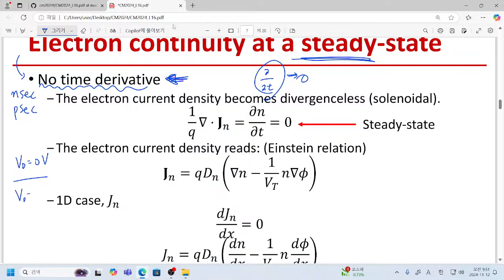Suddenly you increased the voltage up to 0.7 volt. So it introduced a huge difference in the boundary condition. What will happen? The device will take some time to reach a new steady state solution. But please note that in our modern devices, it takes just the order of a nanosecond or picosecond to arrive at this new steady state.